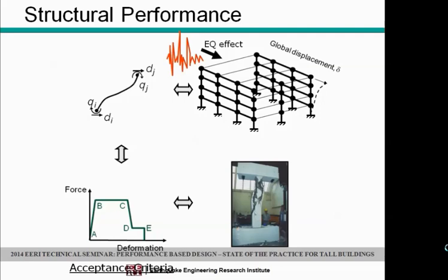Interestingly, when we do this today, we are using representations of the hysteretic performance of the elements that were really developed back in the mid-1990s, and we're thinking static analysis. We only represent, as I'm sure Greg Deierlein will tell you later, cyclic strength and stiffness degradation effects very approximately. We don't do it correctly.